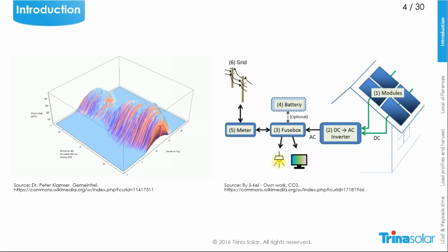If you want the highest rate of self-consumption, especially in applications such as residential, commercial or utility, this energy profile, which is driven by the sun and your needs, should be best aligned, so that most of the energy you produce with your PV panel gets directly consumed in your building or facilities instead of being fed into the grid, to have the best payback time.